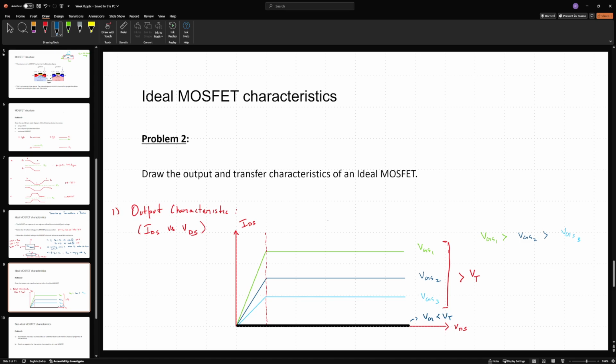The point is we need transistors fundamentally to act as amplifiers and things like that. So I will need a kind of characteristic that will allow my system to gain some power. And for me to have a device that can lead to a power gain, I need a device that is capable of saturating. So that will tell me what is the maximum power I can extract from it. If I have a device that can just give me as much power as I want, then it is not truly an amplifier. A single resistance is never going to be an amplifier.